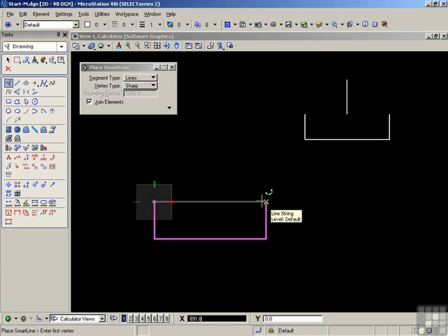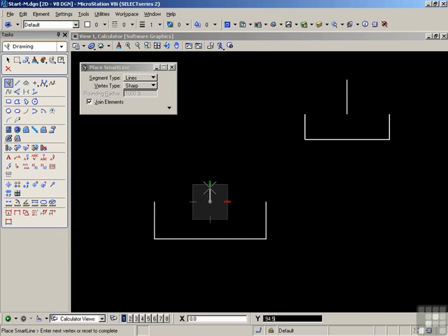So, use the / symbol for divide. There's my divider pop-up. Enter 2 to find the halfway distance. There's the new tentative point, halfway along the dynamic line. I accept it and drag upwards. Very straightforward again. And the calculator has done all the work for me. You'll find a couple of other examples in your AccuDraw exercises file.